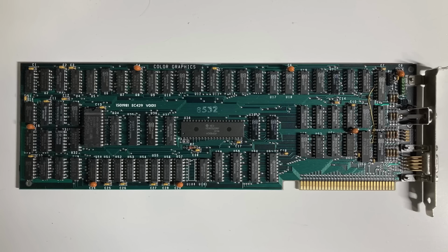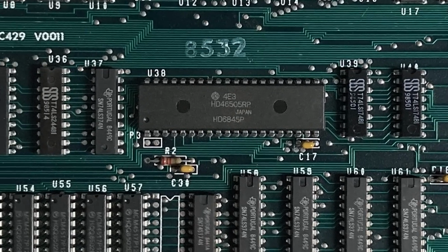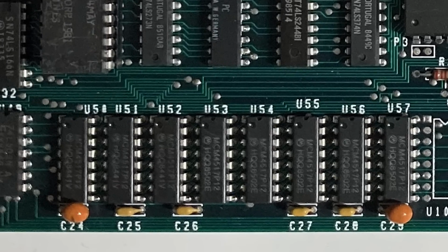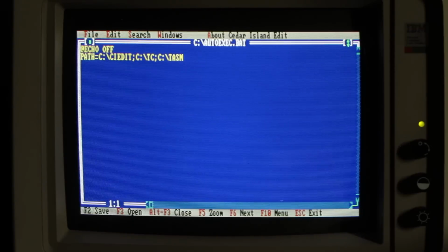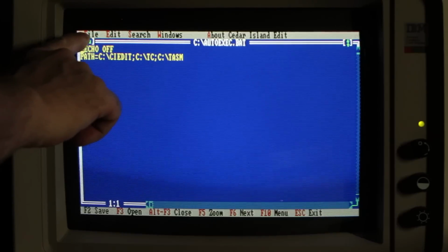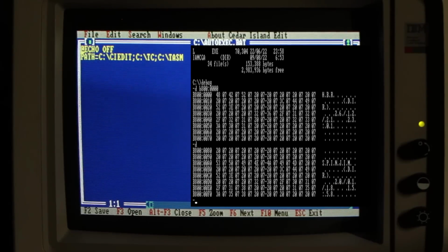Now, of course, the CGA card uses that character address as a lookup into video RAM. And it's in video RAM where we specify which characters should be in each position on the screen. And this is done using ASCII codes. So each of these is a byte, so there'll be one ASCII code byte for the F, then another byte for I, then an L, and so on in video RAM.